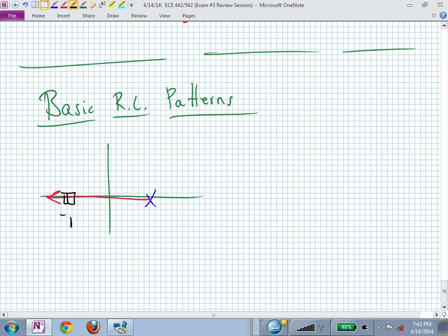It might be starting outside the unit circle. Then you have a lower limit. If this is now 1 right here, then you need to know what's the gain to get me to the triangle. That's my minimum K. The gain to get you to the square is the maximum gain for stability. Is that clear? All of that from that picture.